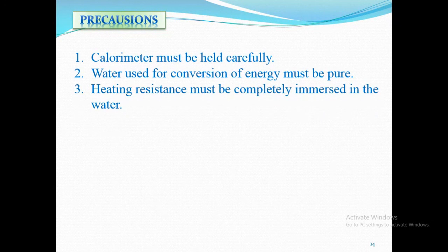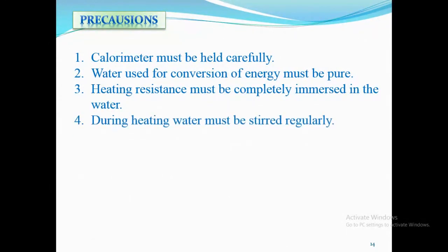Heating resistance must be completely immersed, completely dipped in the water, as I told you in the beginning. If it is not immersed properly, the temperature sensor will not give you the correct reading, because heating is not that much, because it is above the water. During heating, water must be stirred regularly. If you don't stir the water continuously, you will have a wrong graph. That's all. Any question, please?